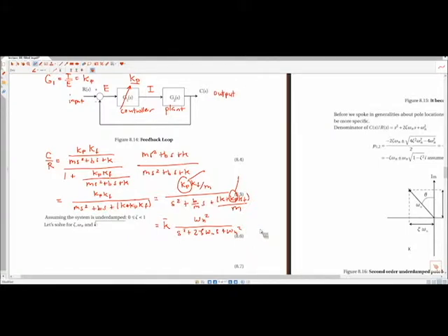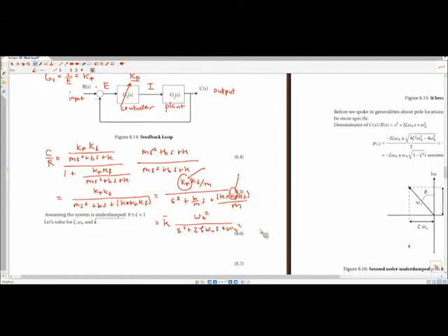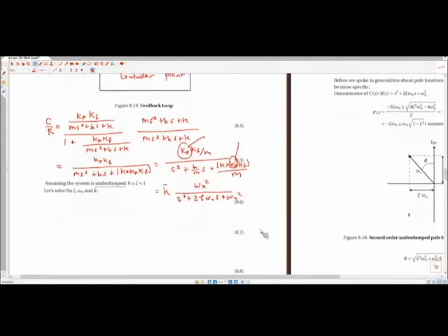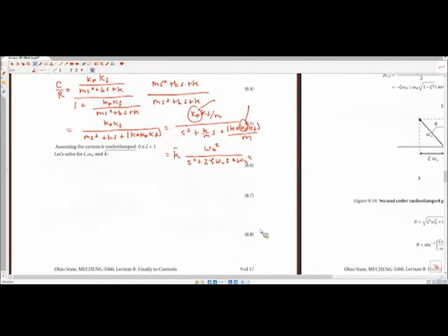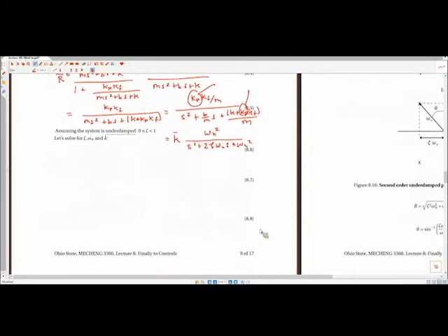Any questions about that idea, how this acts like a second order underdamped system? Okay. So then the question becomes, what is the natural frequency? What is the damping coefficient? This looks a lot like one of the problems we saw that was due on Wednesday with a fluidic system, but this is now a feedback system. So this becomes a matching exercise.